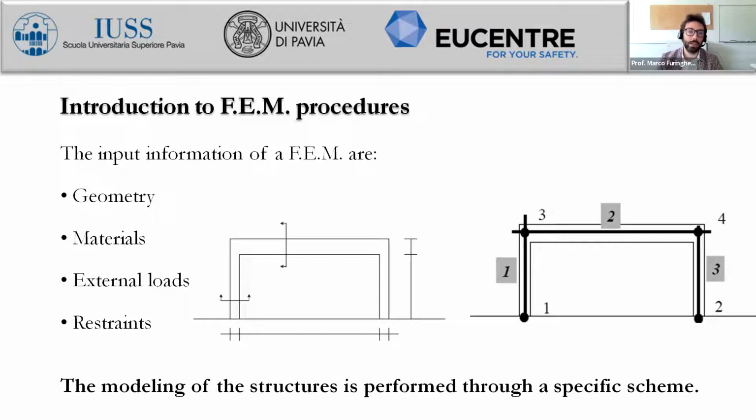So we will also be able to observe some extrude view of the overall structure, so that also frame elements become three-dimensional. The extrude view provides actually the three-dimensional view of each frame element. So you will not see just the centroidal line, but you will see the centroidal line together with the cross section for all the sections. And so your structure actually becomes alive with the